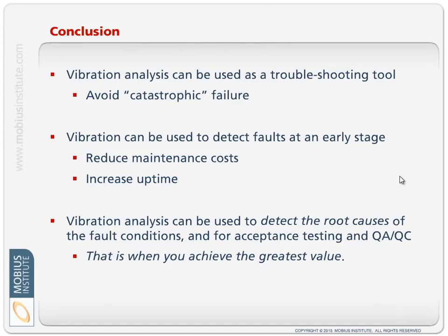because if we detect those root causes like unbalance, misalignment, lubrication problems and soft foot and so on, if we detect those early and correct them, then the bearings probably won't fail. And depending on your industry, we might improve quality, we may reduce energy consumption and all those things if we eliminate those root causes. But whereas vibration can be used to detect the root causes, we can go even a step further and say, let's use vibration to try and prevent the root causes.